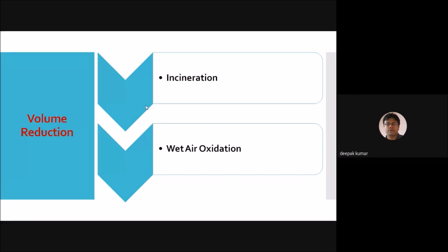Combustion. And generally the temperature used is 1250 Fahrenheit up to 1400 Fahrenheit. All types of sludges, whether primary, secondary, raw or digested sludge, may be dried and burned.